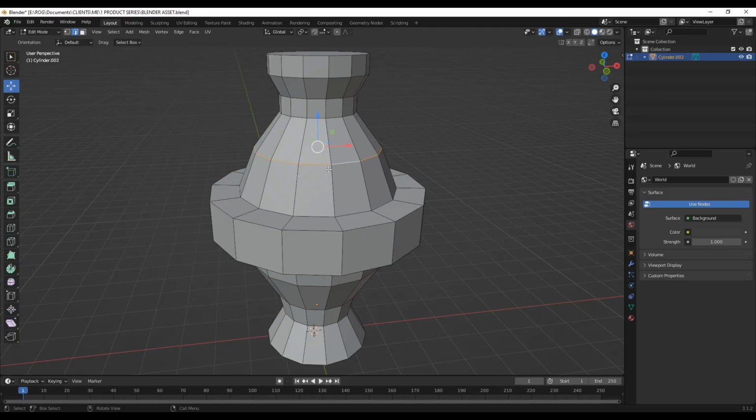So another thing we can do to this loop selection here is to slide it around the mesh. If we currently move it, you see that it's affecting the shape. But if we wanted to just slide this along these other edges, what we need to do is hit G twice on our keyboard. So if I hit G and then hit G again, it will bring up the slide tool and I can just move up or downwards. I need to slide it around this particular edge we're seeing here.